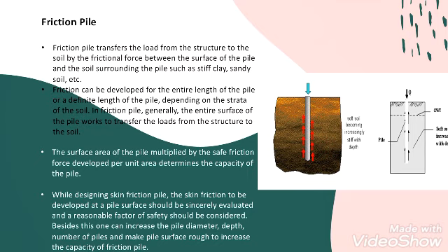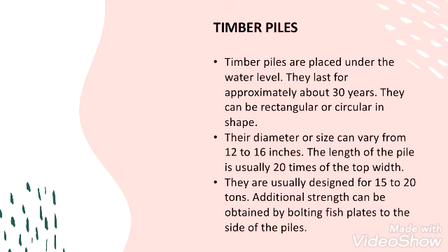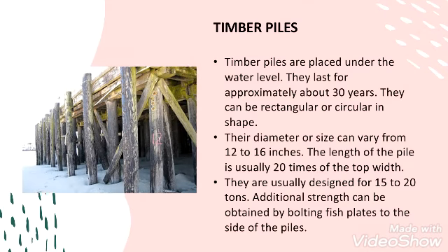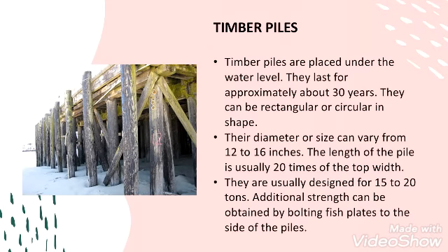Timber piles. Timber piles are placed under the water level. They last for approximately 30 years. They can be rectangular or circular in shape. Their diameter or size can vary from 12 to 16 inch.